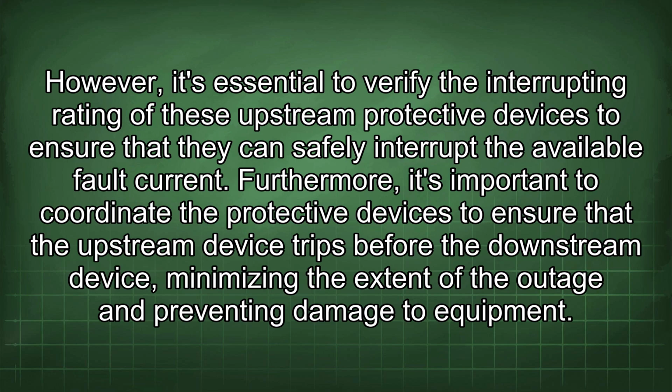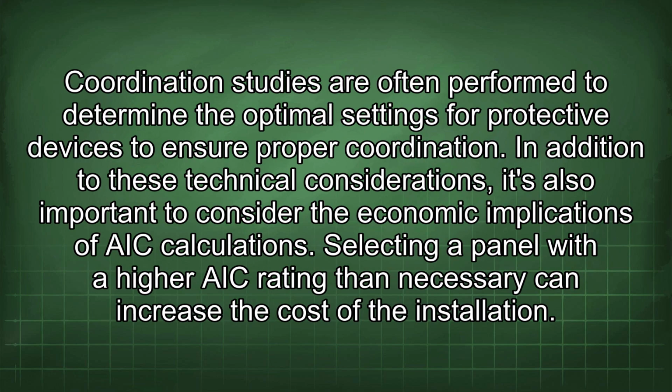Furthermore, it's important to coordinate the protective devices to ensure that the upstream device trips before the downstream device, minimizing the extent of the outage and preventing damage to equipment. Coordination studies are often performed to determine the optimal settings for protective devices to ensure proper coordination.